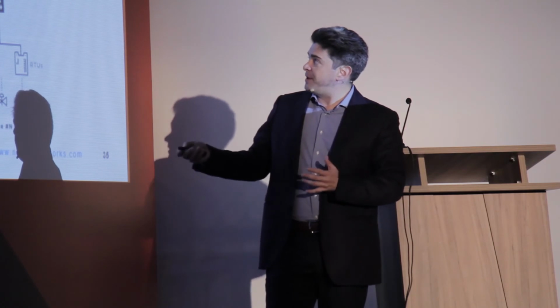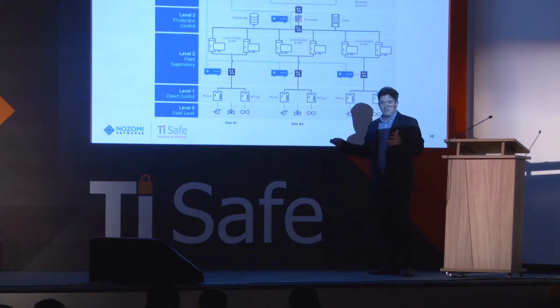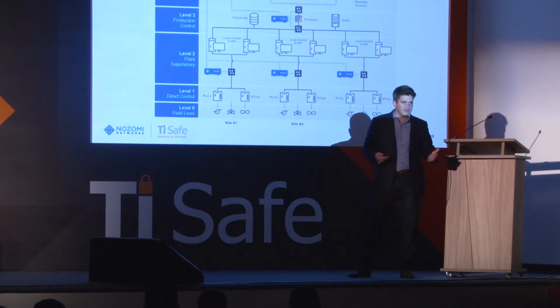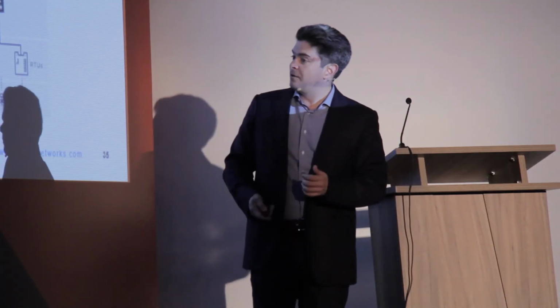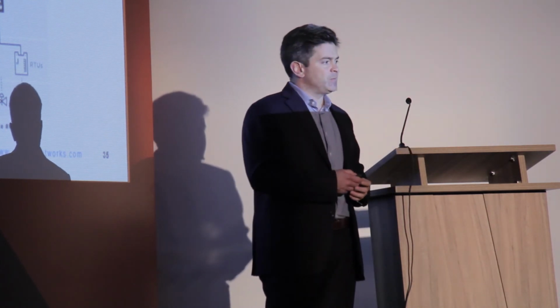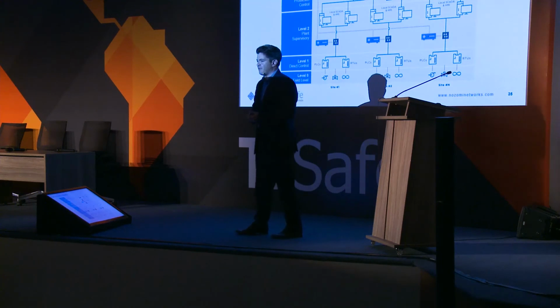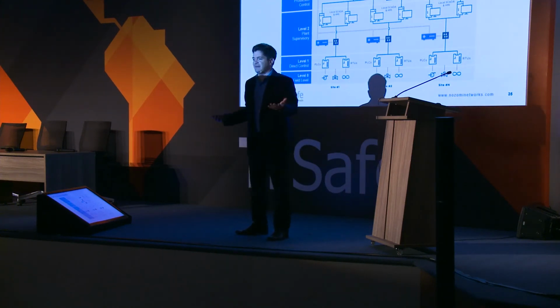And for those distributed infrastructures, you want to make sure that you are able to connect with your SOC or NOC. You may already have a SIEM. As we all know, SIEMs are all about logs. We really don't have logs with context in the industrial control network, so you need context provided to the SIEM. If somebody sends a SIEM an alert that says your furnace is at 400 degrees, that doesn't mean anything to a SIEM, right?